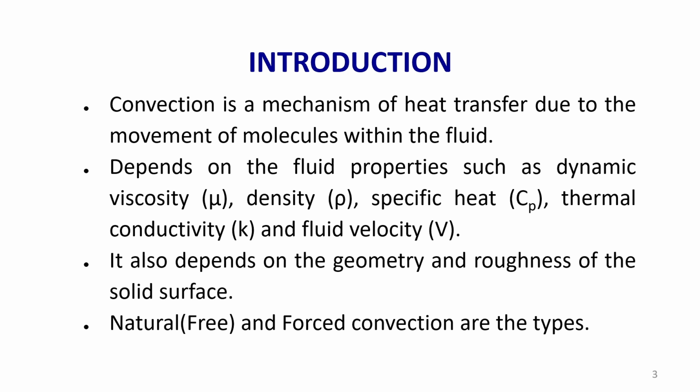Then convection depends upon the Cp value, thermal conductivity and fluid velocity. It also depends upon the geometry and the roughness of the surface on which the fluid is either passing over it or into it, external flow, internal flow, etc. And we will see the difference between natural convection and forced convection.